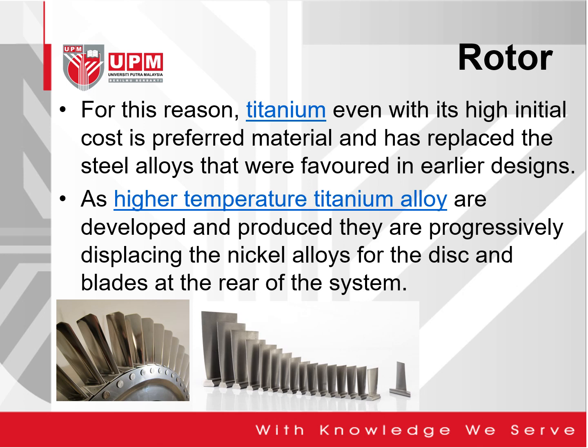So for this reason, we use titanium. Even with its high initial cost, it is the preferred material and has replaced the steel alloys that were favored in early designs. As higher temperature titanium alloys are developed and produced, they progressively displace the nickel alloys for the discs and blades at the rear of the system.